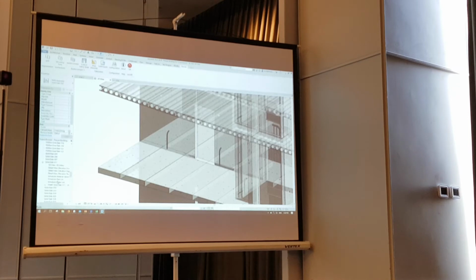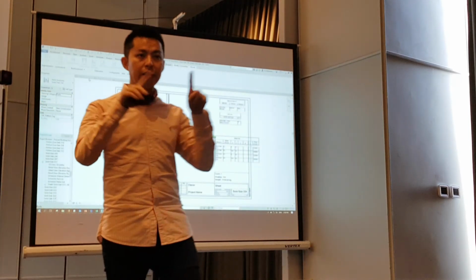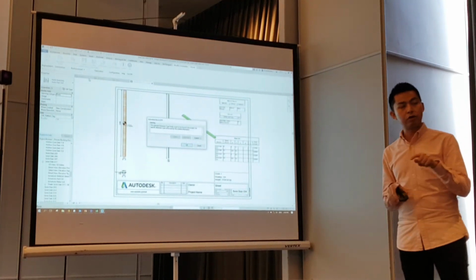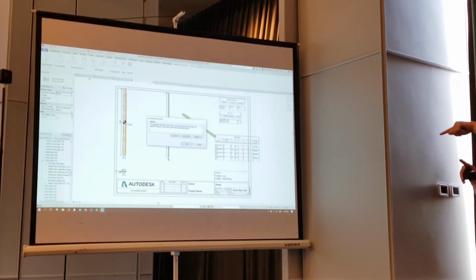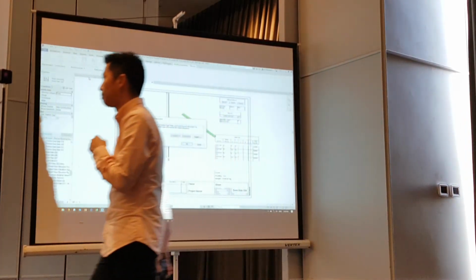Now, the next thing we need to do here is convert this one into shop drawings. All you need to do here is select the assembly and click on the shop drawing itself. Now, the settings or the layout of the shop drawings is reading from the template. If you go into the program data folders, you should be able to see there's one settings for you to configure the layout. And then from there you can do your own settings and so on.